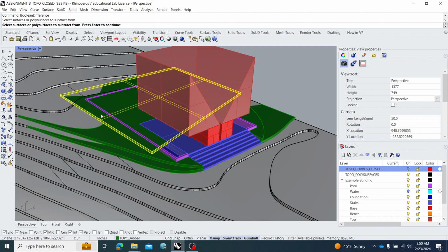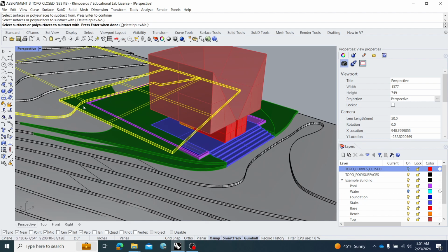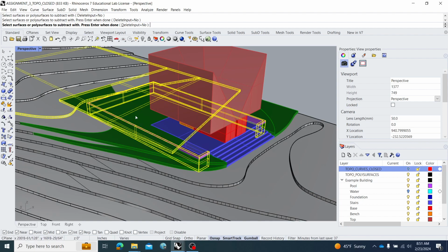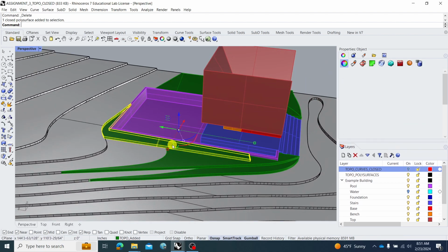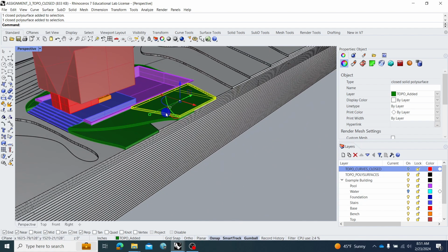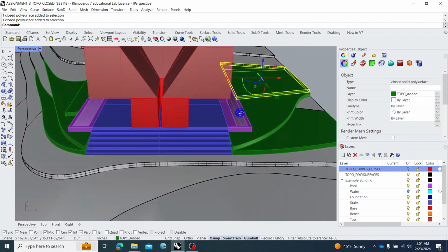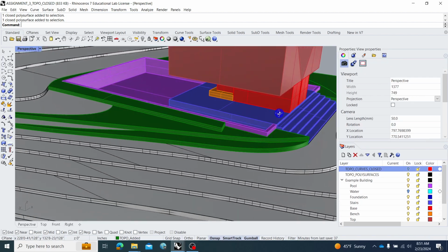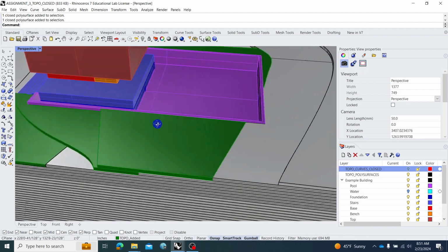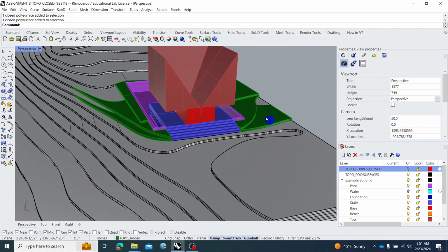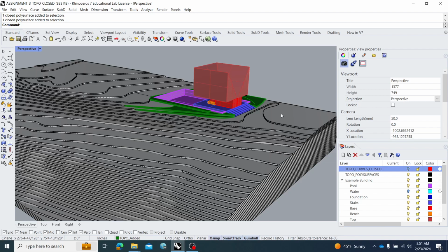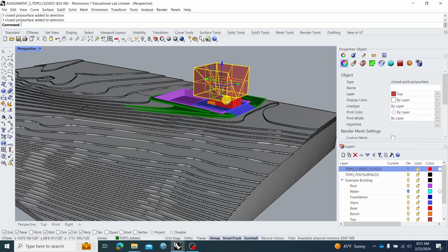We want to subtract from this new topography using the existing terrain and the pool wall. So we delete that interior piece. Now we see that this other layer that we've created, while it may be a little bit more straight and angled, still works fine, and it has kind of merged or filled in some of these weird areas that we had. Okay, so that is a way that we can subtract from the terrain, but also add certain elements of terrain to make our building work.